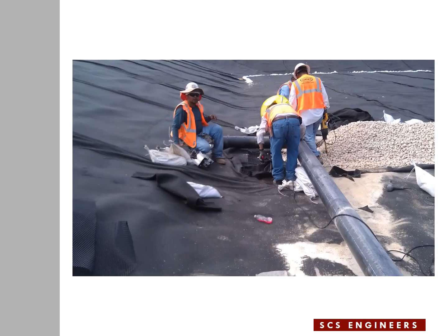At this point I'm going to show you a number of pictures from a recent construction event. This slide shows the completion of the leachate collection pipe at the high end of the cell. The perforated pipe is the leachate collection pipe. Gravel is placed over the pipe until the near end of it. The solid pipe in the foreground of the slide is the pipe that will bring vacuum to the gravel bedding around the leachate collection pipe.